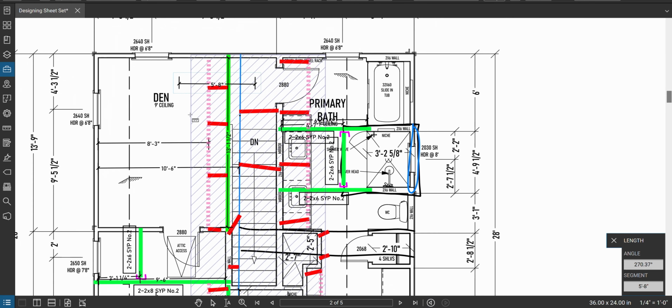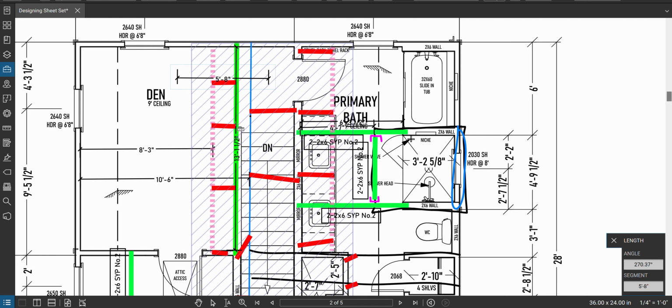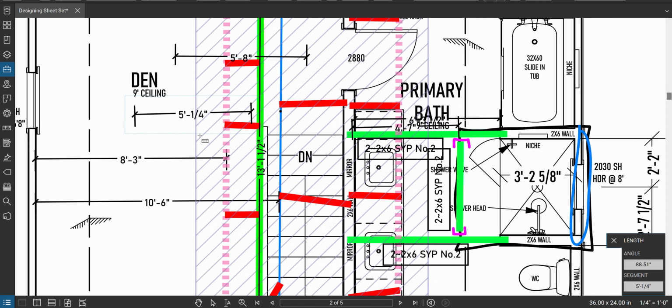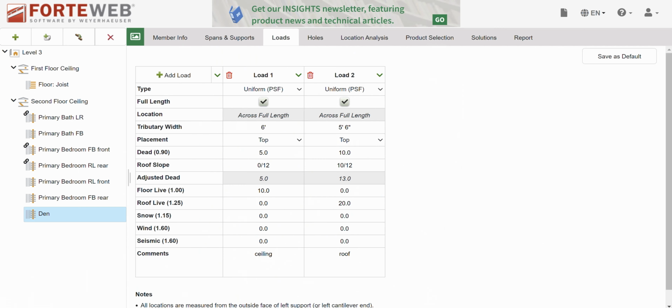How much roof? Okay, so I'm responsible for this purlin, here's the pink. This is the purlin, bracing down to the beam. The roof rafters are supported here at the purlin and at the wall, so I'm going to grab that half distance. Now the rafters run up to the ridge. The ridge is supported to this wall, not my beam. So that's where I'm done. The ridge is going somewhere else. So halfway from the ridge to my purlin is what I'm responsible for. 5'1", let's call it 5'3", just round up a little bit. 5'3" on top, it's all the same, great.